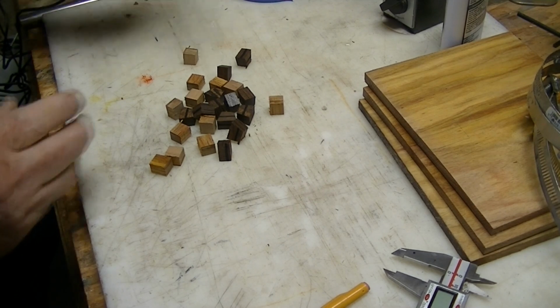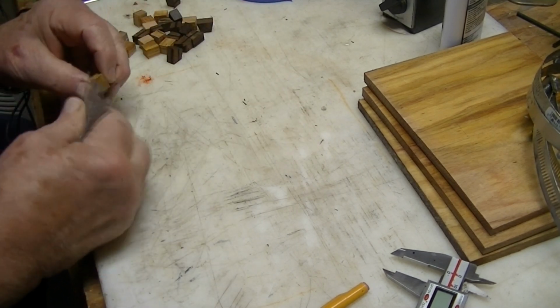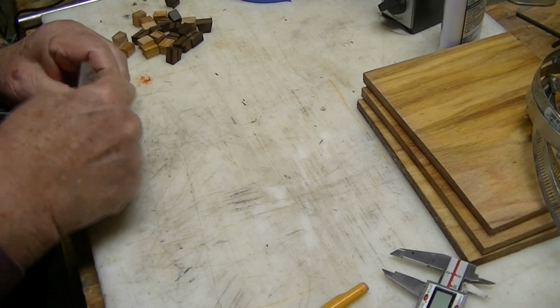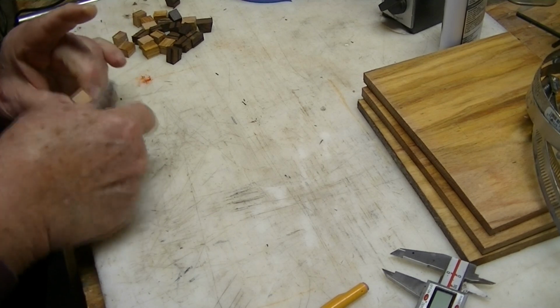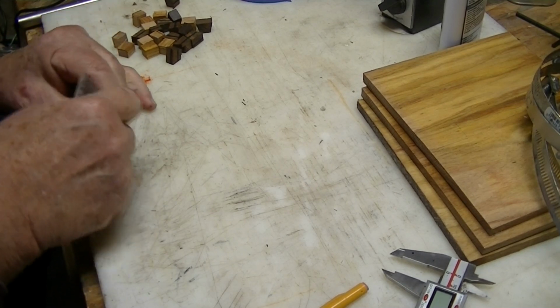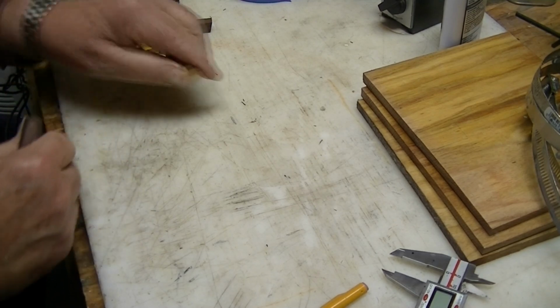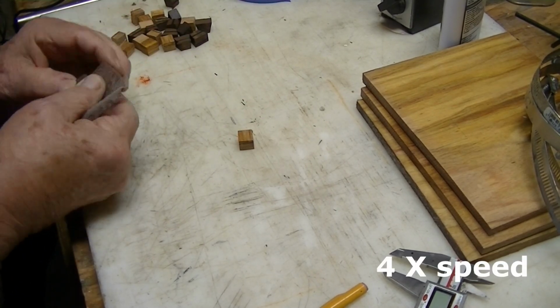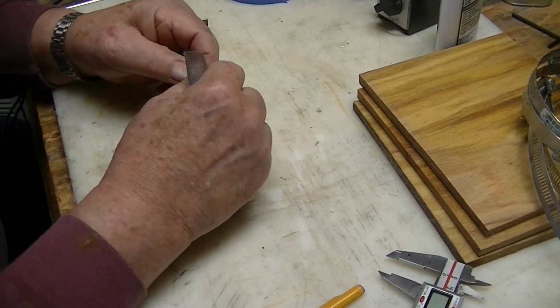Now the tedious job comes. Each of these pieces needs to be individually sanded. All the edges cleaned, deburred. I don't want any fuzzy wood remnants to get into the joint and give us an open joint. So what we're going to do here is sand each individual one, and then I'm going to mix the segments